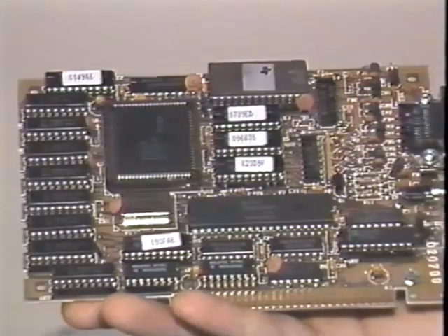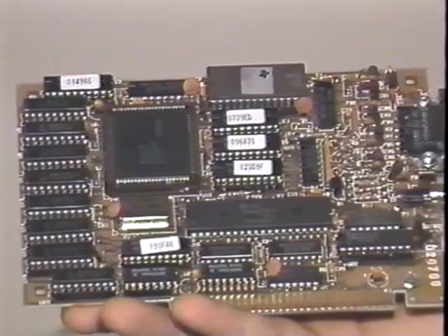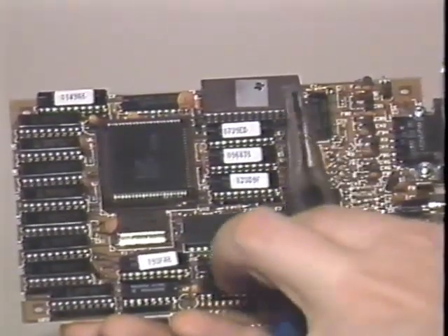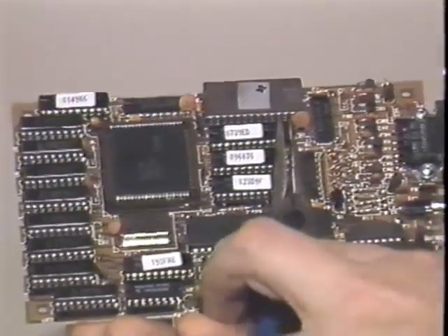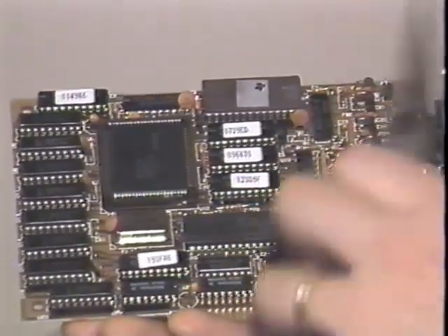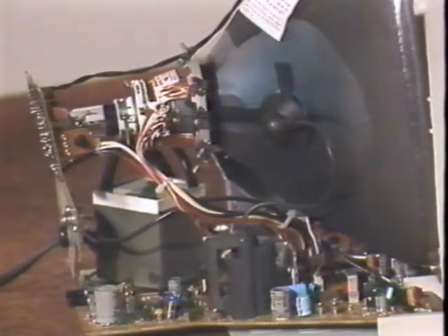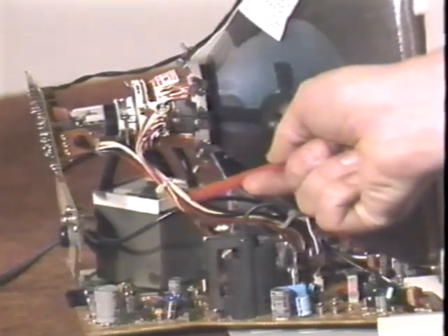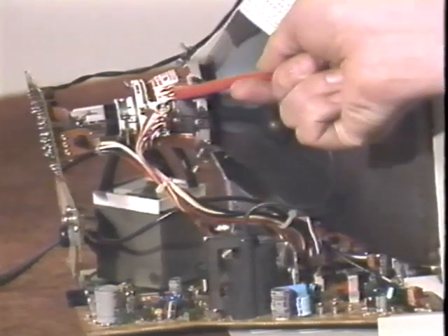Video generator circuits designed to work with either monitor type will generally have switches or jumpers to select color or monochrome mode. If you do not select the correct setting, no video will be displayed on the monitor. Regardless of the connector type, the monitor will use the information from the computer's video circuit in the same way. One of the major functions of the driver board is to produce horizontal and vertical sweep signals which drive an electromagnetic yoke, causing the electron beam to move around the screen.